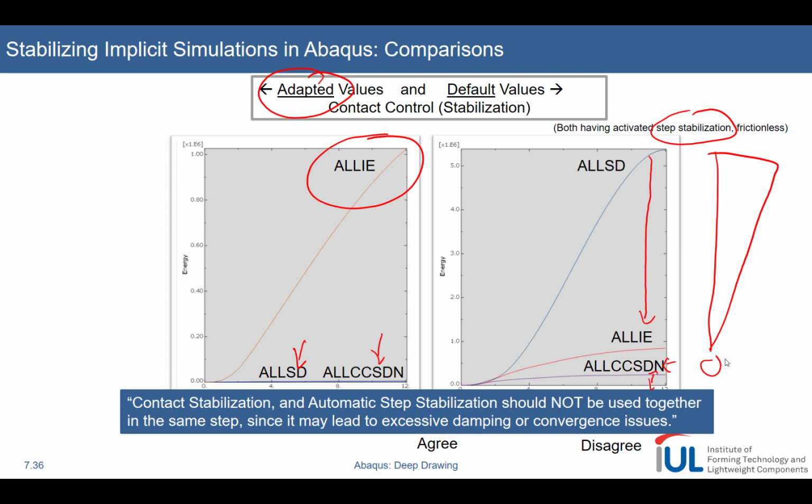But the computational time is the remaining drawback, and an important factor to consider is that implicit simulations, using multi-core simulations, can be easily split up so that you can do a very nice parallelization of your problem. So if you have large problems, using many cores is a very good idea in implicit simulation. In explicit simulation, you can't use the same mathematical approach to parallelization as you can in the implicit case.